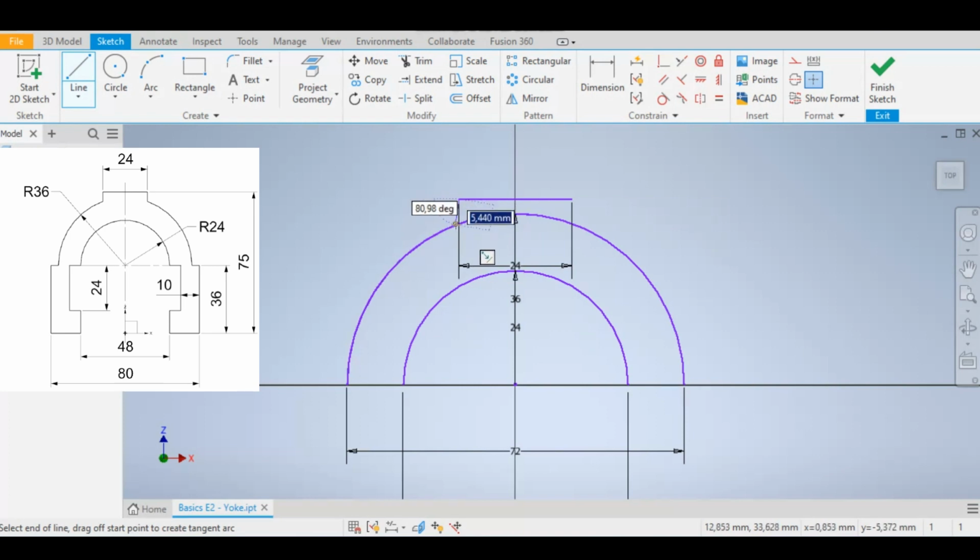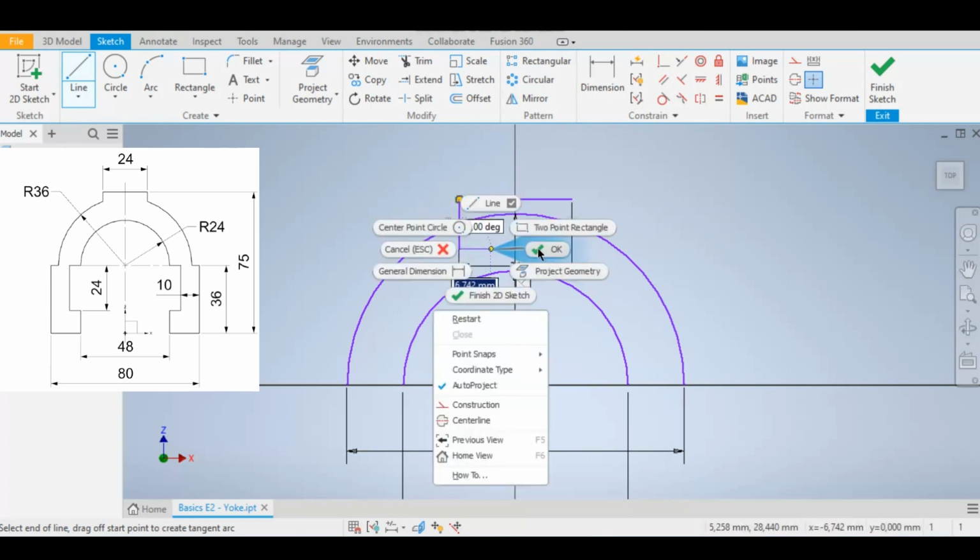Even if it's slightly, if it's by 1 degree or 0.02 degrees, as you can see on the screen, this can happen and it will affect your drawing. And once you get to extrusion and measurements of your part, it can have an effect. So I'm simply going to draw on a 90 degree. I'm going to draw through the line and I'm going to select my arc there.